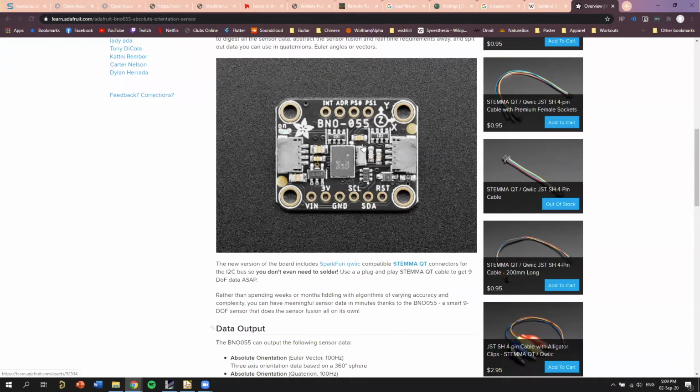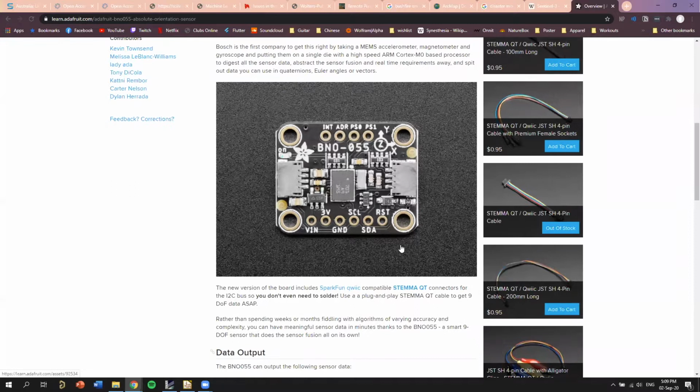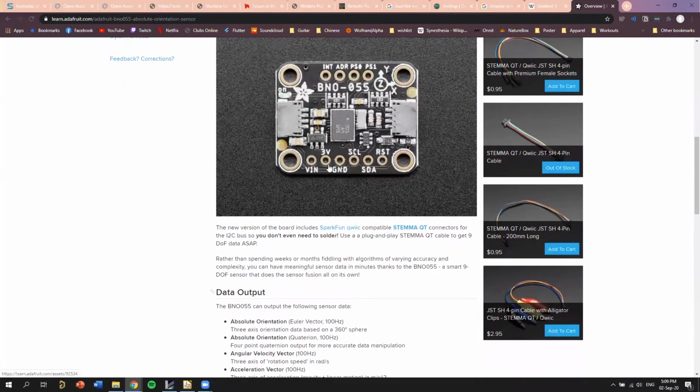What we want on our flight computer when we're designing a PCB is essentially to design this whole breakout board. So we want to grab this chip here, say, okay, what components do we need around it to make it work? So that would be capacitors, resistors, they've added an oscillator here, which we can decide whether or not we want to do that. LEDs, plugs, and basically interface it to what we want to use as our main controller. So rather than having a main controller on a different board, it's all integrated onto one board, and it's very nice and easy to use.